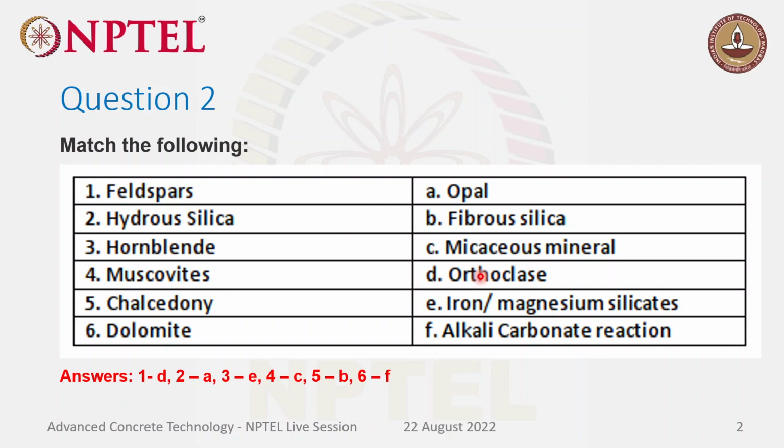How will it affect? Because obviously the cement manufacturers are not totally going to change or play with it. Even now it's going to be dicalcium silicate, tricalcium silicate, tricalcium aluminate, and tetracalcium aluminate. It's going to be the same. The same type of products will be forming, and the amount of product left unreacted will be very, very less, because it's an old structure. It has served for more than 10 to 15 years at least, I suppose.